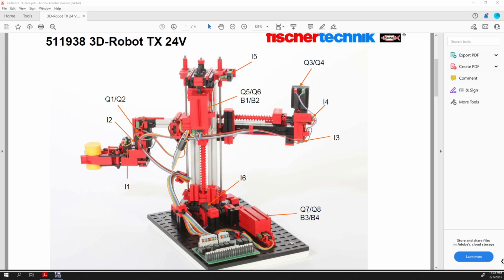All right. Let's think about it this way. If your code is running as efficiently as possible, which in this class we are probably pretty close to that, you're running at maybe 1 millisecond loops. So it takes 1 millisecond to run your entire code before it runs your entire code again. That means your code is running 1,000 times per second.